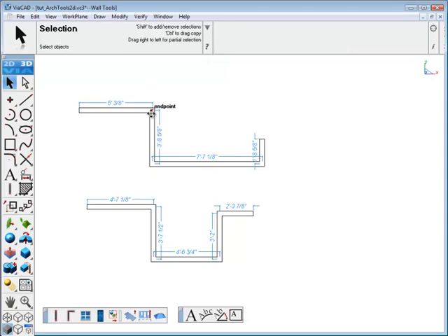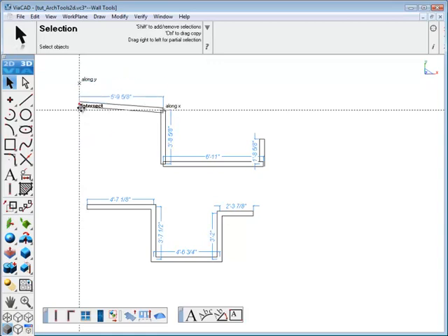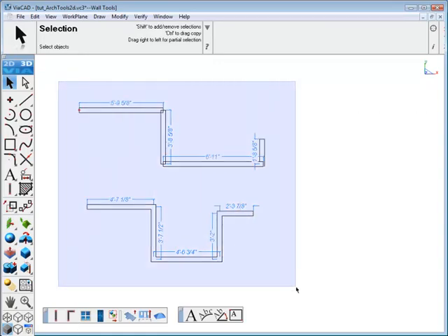To move a wall and maintain its relationship with other walls, drag around the endpoints of the wall and its adjacent walls. Move it to a new location, and it keeps the endpoints connected. To move a wall endpoint, simply drag around that single corner and drag that point with your mouse.